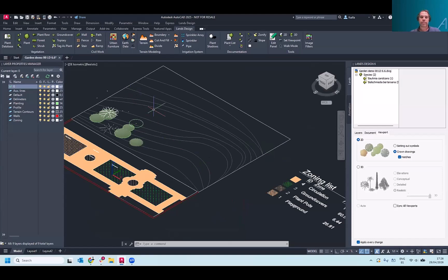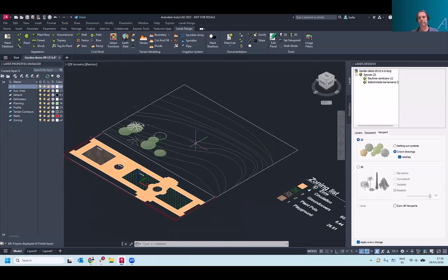Okay. These curves are meant to be like contours that are separated at regular intervals, but they could be curves totally messed up in the 3D model space. We could even create terrains from curves and points, and the program will take all these values of the points of the curves and the individual points and will generate a topography out of this information.